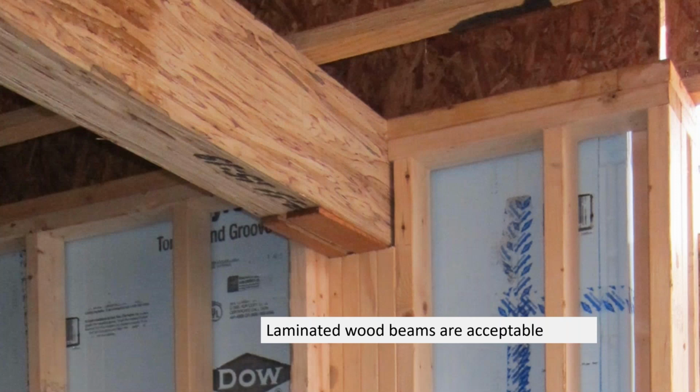This is a laminated beam, and a lot of the mass production builders will use a laminated beam. It's a lot lighter to maneuver. It doesn't require a crane to drop it in typically. It is basically pieces of wood that have been laminated together to be a certain width, whatever the engineer has designed, to carry the load of the floor above. So they don't always have I-beams in the houses. Sometimes you will see the main beam is made out of wood, and that's what this is. This is a laminated wood beam.